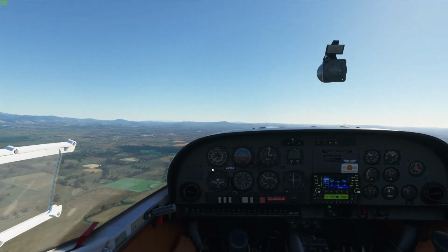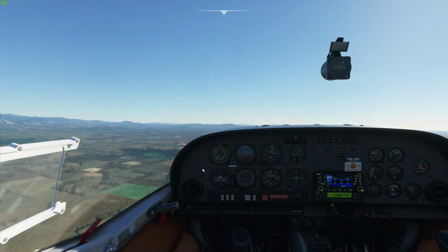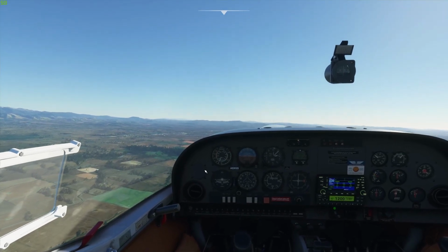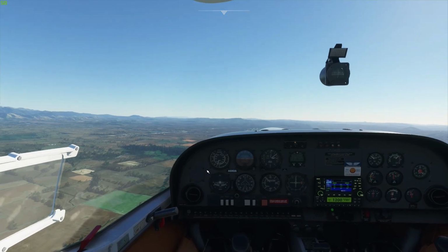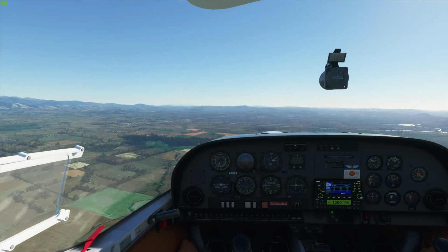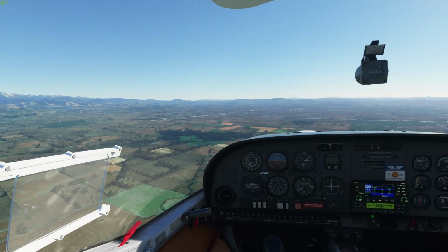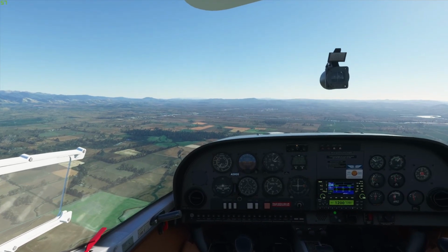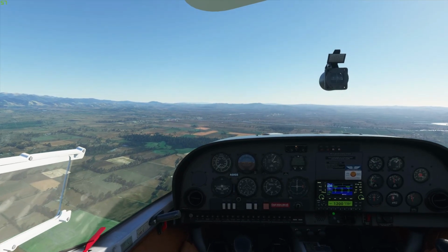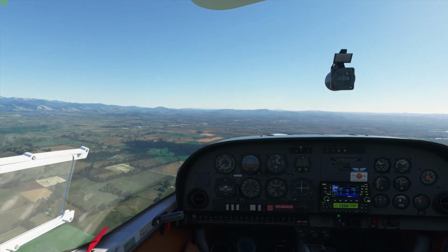As the nose goes up, the speed will reduce. And in a stable aircraft, it should return more or less to where we started from, I should say. I'll put a little bit of aileron, but I'm not touching the stick at all here. So we're on our second Phugoid now. Now that's about the original speed, 95 knots. So it's definitely dampened out.